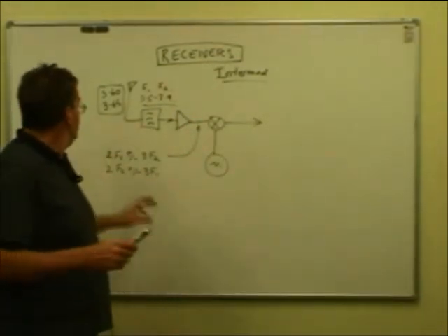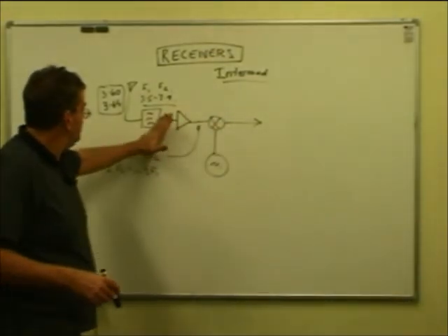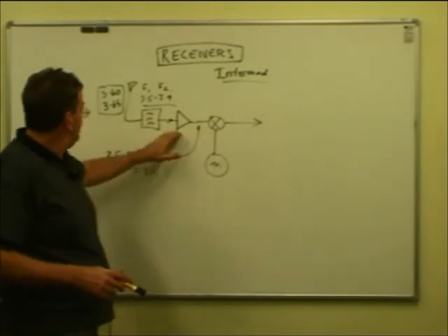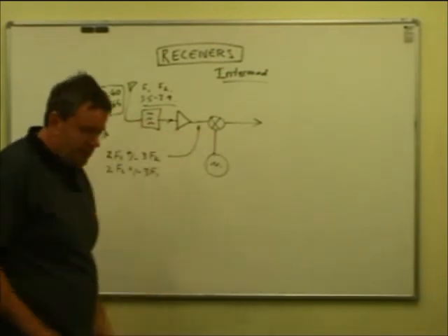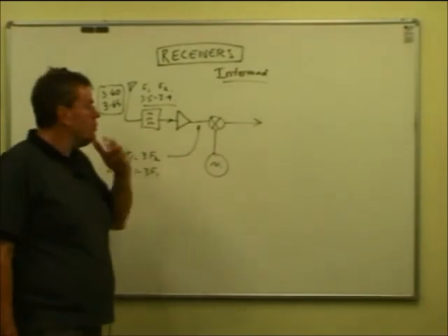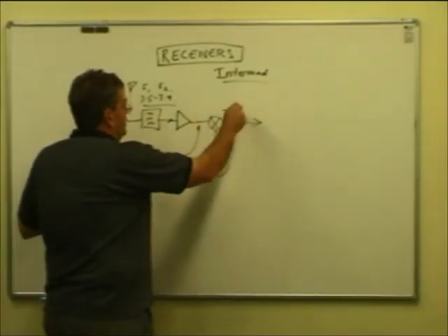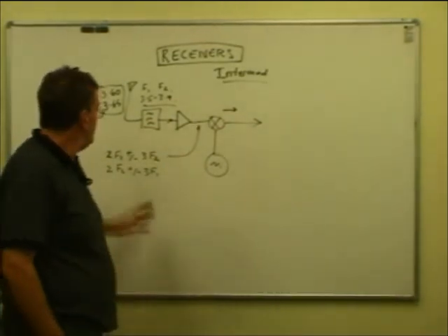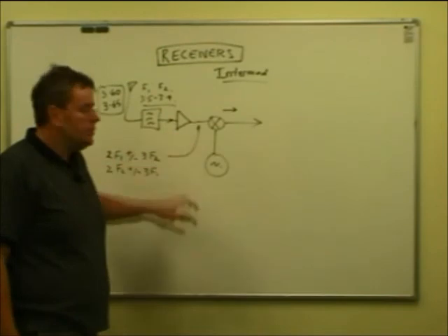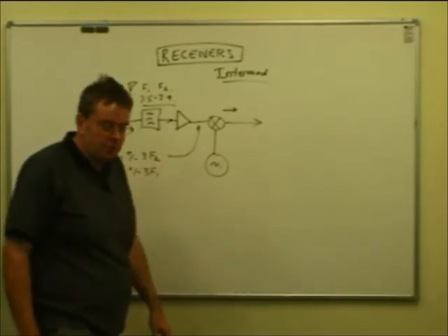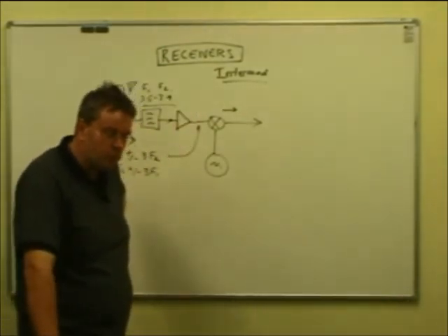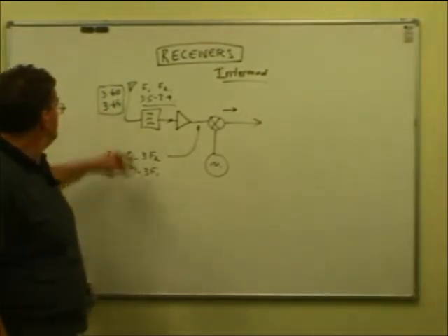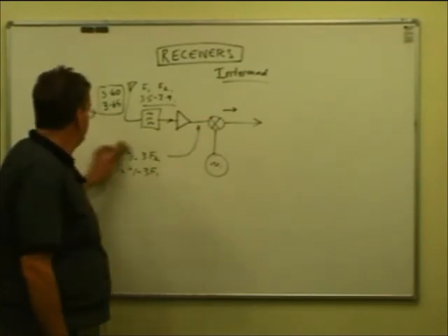The problem is, if our poor old front end, the filter, not normally much of a problem, but certainly the amplifier and the mixer, if we've got very, very strong signals coming into our receiver, we get new signals created coming out of here that don't exist on the aerial. They've just been manufactured out of the blue by flaws in the receiver and the mixer. Generally it's when they're not very well designed or just built on the cheap that this will happen. So if you do the maths for 3.6 and 3.65, well, just forget the formulae.